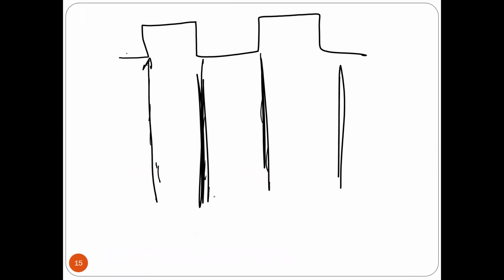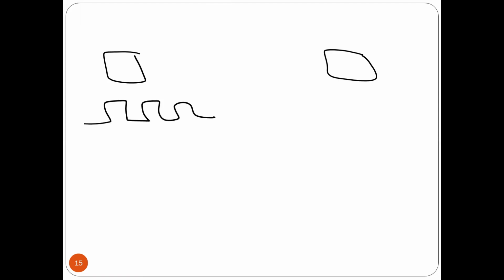Quickly for 1 minute before I end this lecture. So why do we suffer from lack of synchronization? What is the reason for that? I'm going to tell you why. Very simple. At the sender and the receiver, we use an electronic circuit to generate a clock, what we call a clock. Here also we have a clock. Is that okay? It is going to be very difficult to generate exactly the same clock. This is something normal. This is because the circuit has electronic components like capacitors, it has a crystal and these things, and there is no way to get exactly the same values. Also aging, or temperature has some impact on that.